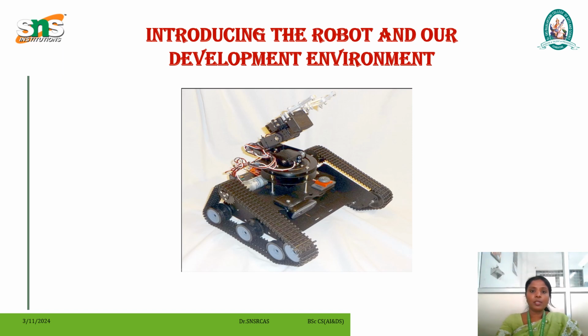If we want to go straight ahead, we set both motors to the same forward speed. If we want to travel backward, we reverse both motors by the same amount. Turns are accomplished by moving one motor forward and the other backward, which makes the robot turn in place, or by giving one motor more forward drive than the other.